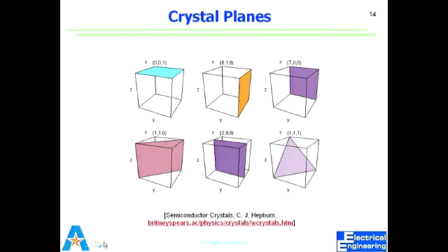So essentially, all other planes are equivalent of these planes. Does it make sense? All other planes are equivalent of these planes. I get everything except 200. How is it 2? Is it 0.5 inverted? Yeah. So we flip those numbers. Remember, zeros are infinity, so inverted. You have the unit cell, so you have to divide it with the unit cell and then you flip it. That gives you 2. Right?